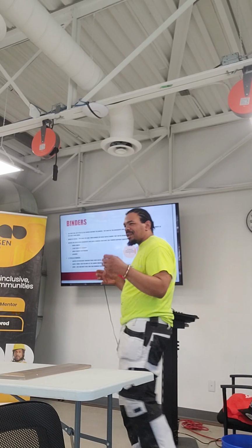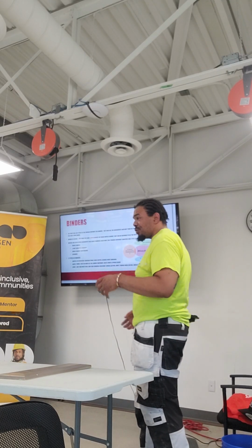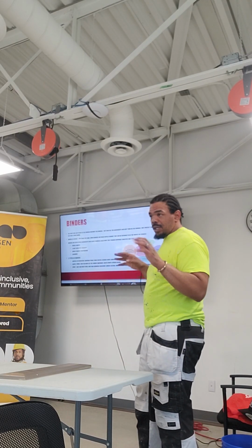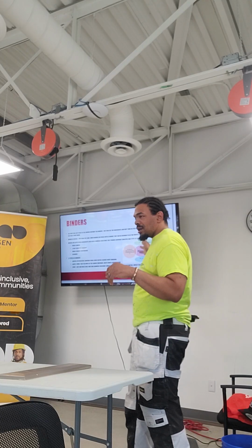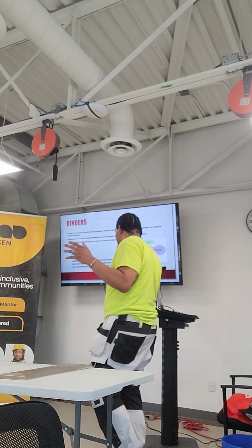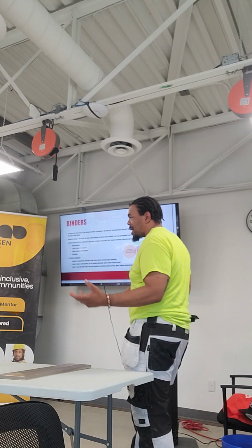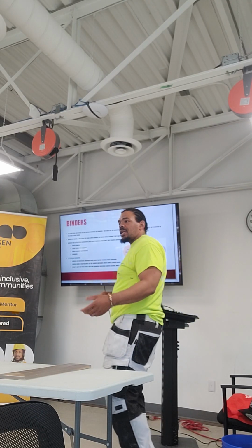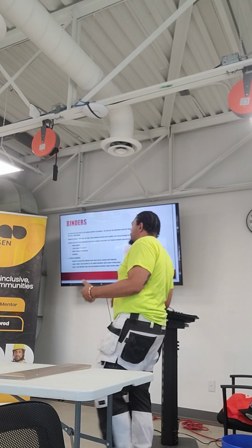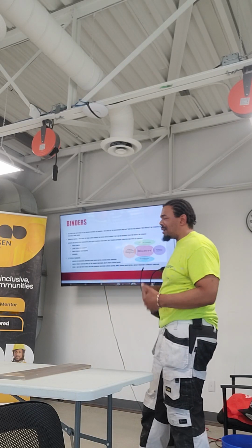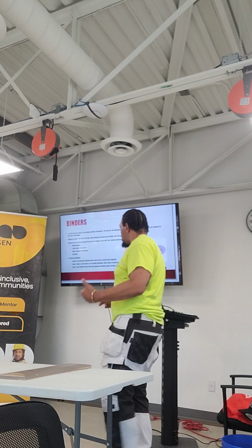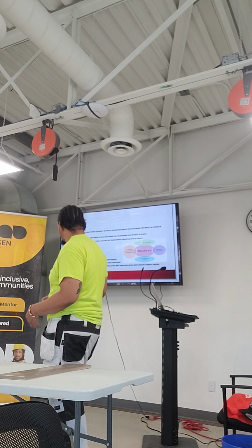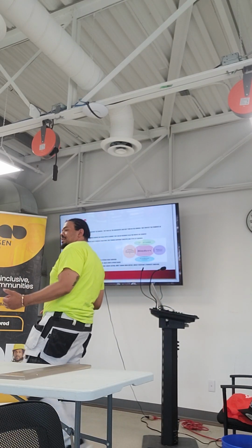We're going to get into some of the chemistry behind some of this stuff today. So if you want to take notes, please do, or you can take photos of this. But so, two-part catalyzed conversion primers, two-part polyurethanes, two-part epoxies, lacquers, they all have to use these kinds of binders. There are three kinds: you have acrylic binders, you have alkyd binders, and then you have epoxy binders.